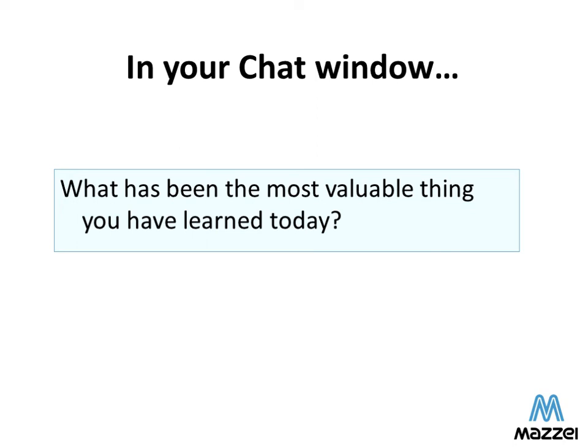Okay, good. Here's a question for you. If there are several recommended choices using the injector selector, is it better to choose the smaller or larger injector? Okay, that's a good question. Yeah, great question. On the pressure reduction method, choose the larger one, especially when you're operating a large farm system.